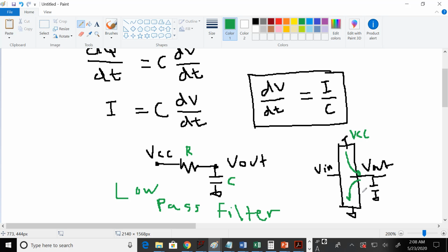But as your input signal goes faster and faster, eventually you get to a point here, and the corner omega is 1 over your RC. And that's the frequency where it starts to attenuate the signal. And if you get too much past that, then your signal basically disappears. So, yes, what we're going to look at next is how to find R and how to find C.